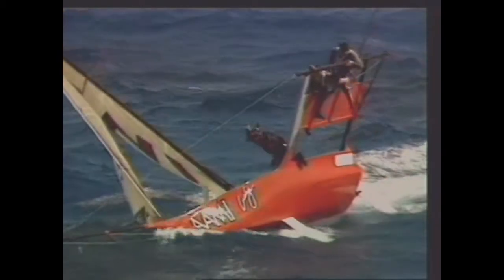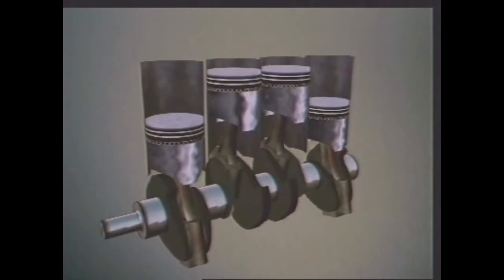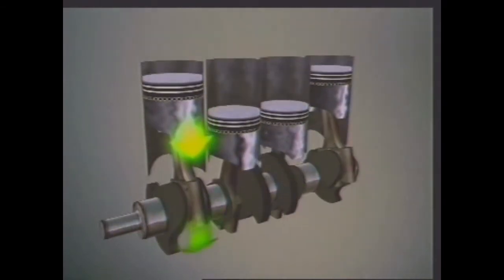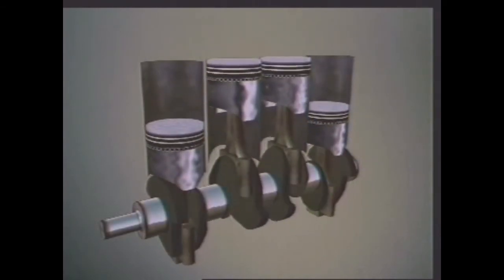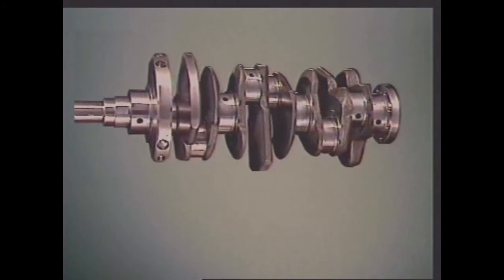Counterweights appear in unusual places. They're essential for some systems to work at all. Crankshaft counterweights help keep the rotating components in balance. They help keep the crankshaft turning as smoothly as possible. The crankshaft turns because of the forces transmitted through the connecting rods. At the same time, it must be held in place. That's done by bearings. They reduce friction and allow free movement.